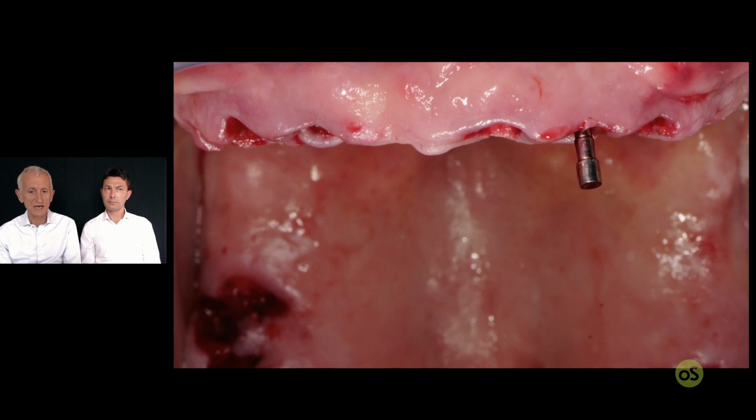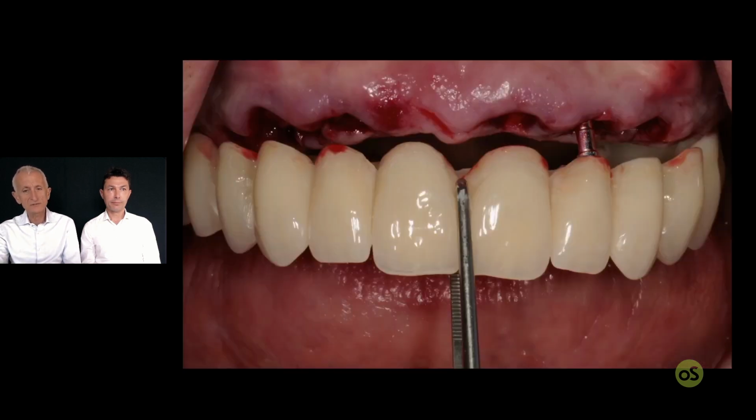I think you should slow down. I think you should just make a little drill with the pilot burr, and then put a pin, then use the shell every time to check if what you are going to do is in the correct position with the correct axis. Because if it is not, you still have all the time and the freedom to change this and to make it better. So no rush,